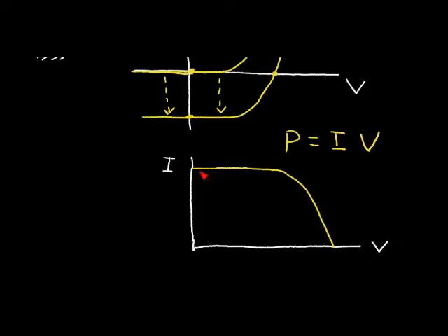So if we are, say, operating at a point right here, or in fact, let's consider we're operating right here. At this point, we have no voltage across the solar cell. So we've, in effect, shorted out the solar cell, and we produce a large current. But since the voltage is 0 in this equation, we don't really get any power, so it doesn't do anything useful.